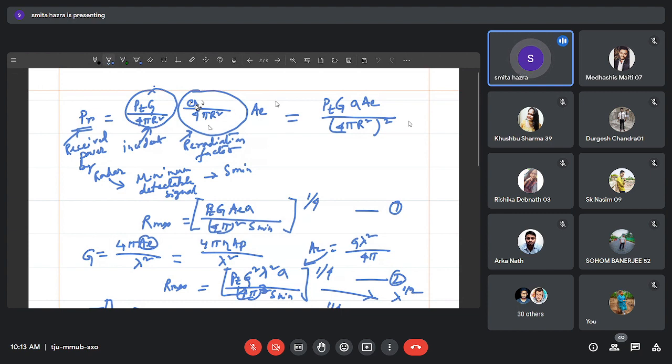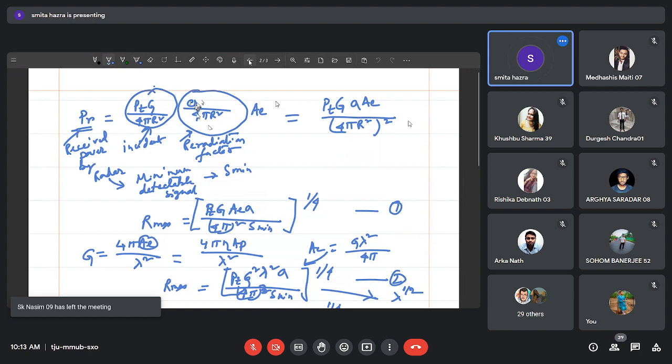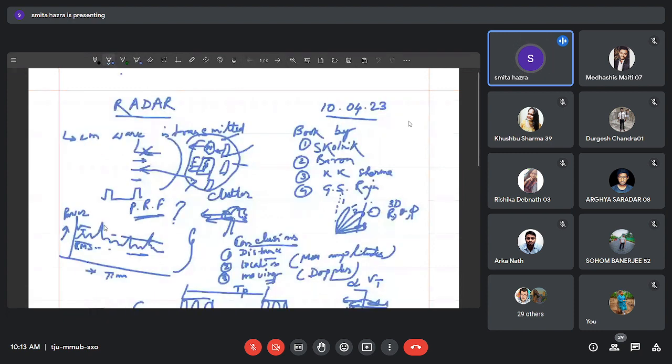So within this sigma, the real object echo is there, but because of the higher level of the VT, it falls to the lower range of the VT. That means it is not able to exceed the level of the VT. So that problem is the misdetection. So these two are simultaneous: if we lower VT, then we are led by the false alarm probability; if we make VT higher, then we are led by the misdetection probability.